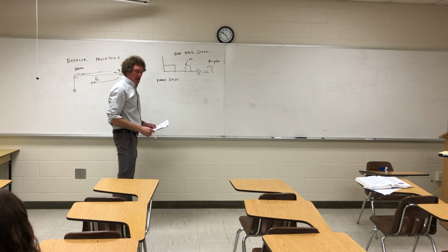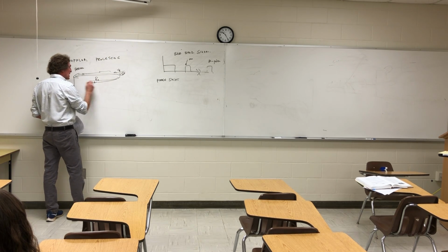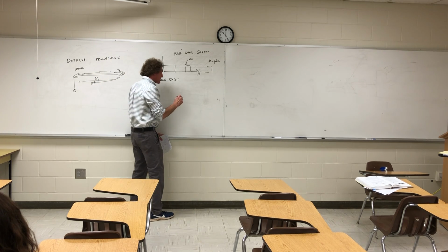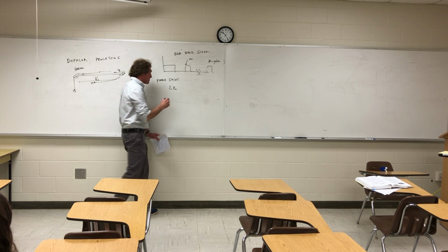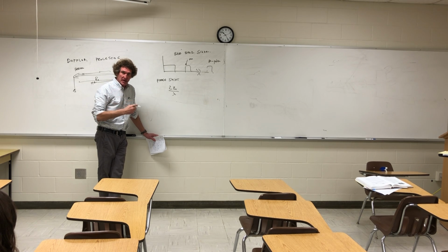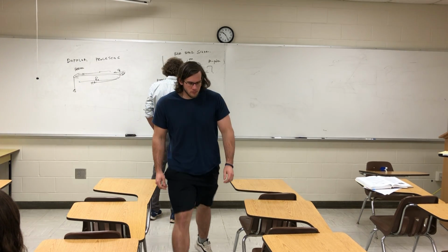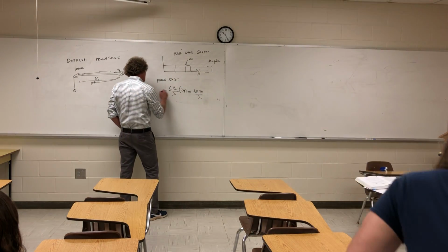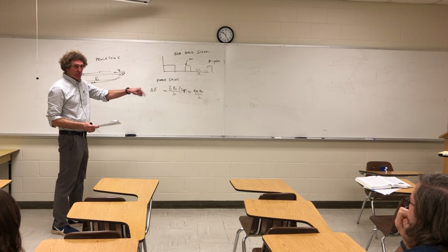All right, first, what do I mean by phase shift? It's the phase shift that occurs when you go out and back. So, we've done this before. We know 2R0 is actually the distance traveled, right? 2R0 by lambda is now the number of wavelengths that the actual signal traveled. It hit and came back. Do you agree? I'm trying to be real simple with this. And we know if we want the total phase change in radians, we multiply this by 2 pi. Now we get 4 pi R0 divided by lambda. And this is the phase change that occurs as the wave transgresses, right?